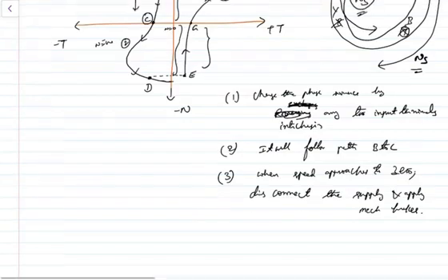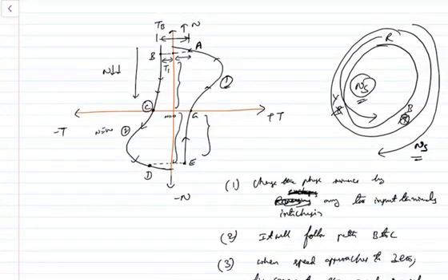Now let us assume the rotor resistance is increased, because in the case of a slip ring induction motor, we can increase the resistance at the time of starting. In that case, the curve will shift a little bit. So the curve will follow some other curve, let us represent it with blue color. The maximum value of the torque will not change, the curve can be shifted. Let us assume I have designed the rotor resistance in such a way that maximum torque occurs at slip s equal to 1, or when speed is equal to 0. So now your curve will shift like this.